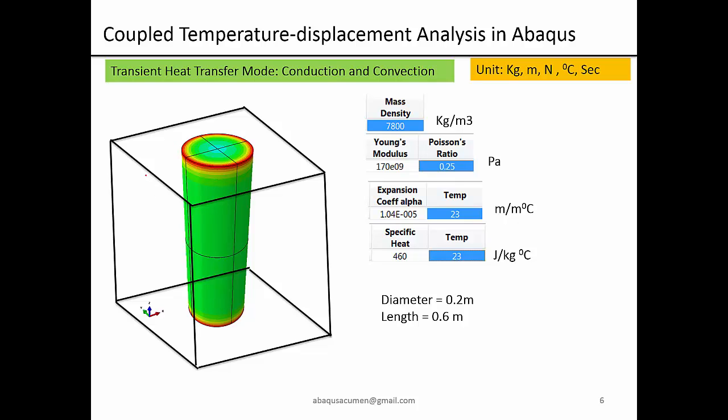We will keep this inside an oven, with the sink temperature at 600 degrees C, and we will give a heat transfer coefficient H, because it is warm air and with natural convection it is acting on the workpiece. We will have a heat transfer coefficient on the outer surface and the top surface, from which heat will start propagating.